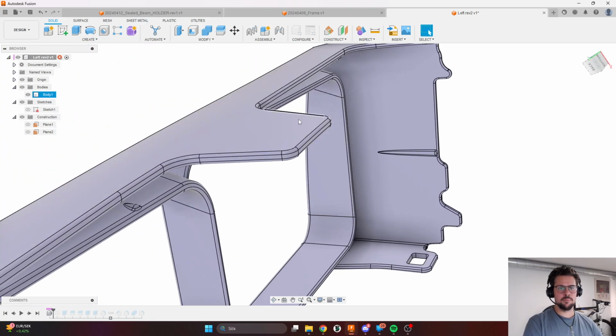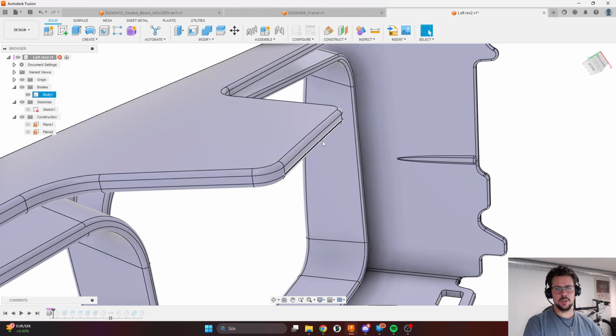To get something to draw from, these planes are not actually completely flat. And because of that, we cannot create a sketch off of that. So what I did first was create a sketch, and from that sketch I created a plane that we could make the original feature from.